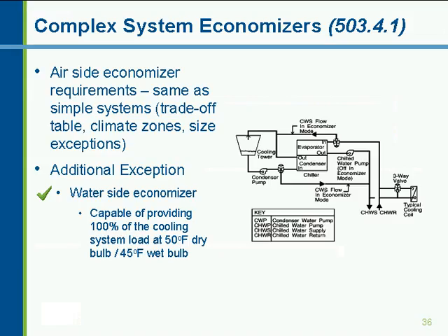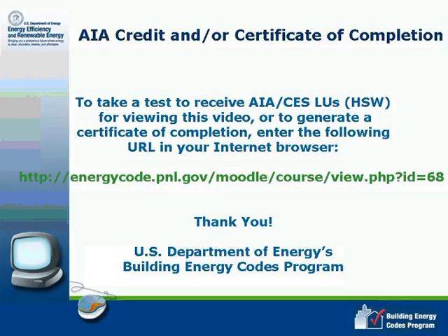Okay, there was a question about system sizing. I mentioned that if you have a single piece of equipment serving both heating and cooling loads, you could size to select the larger of those two. And the question is that this would imply that you could size a heat pump for the heating load, which would result in AC being oversized 300% in zones 5 and above, which is very cold climate zones. This results in reduced humidity removal, reduced equipment efficiency due to short cycling, increased equipment wear, increased first cost, decreased comfort. Are you sure about that?